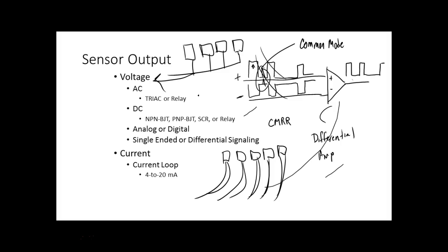So this differential signaling basically eliminates the electromagnetic interference. Like an Ethernet cable, I don't know if we got one in here or not. It's good for 100 meters before you have to re-amplify and send it on. So we can run an Ethernet cable through some pretty noisy environments, over 330 feet. In the old serial interfaces, we were dealing with feet. Unshielded single-ended maximum would be 15 feet.